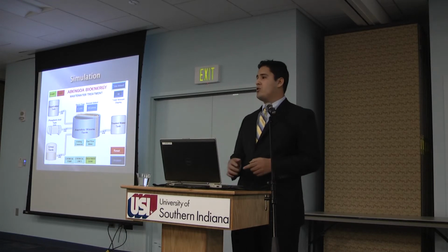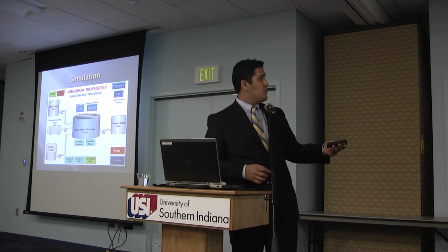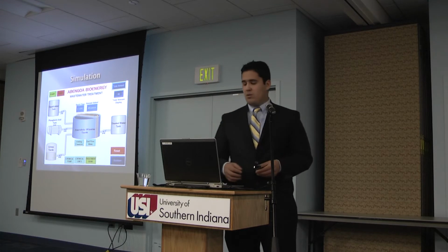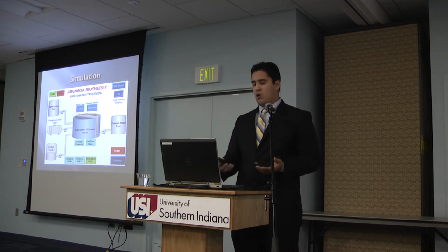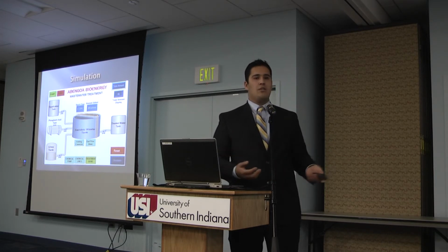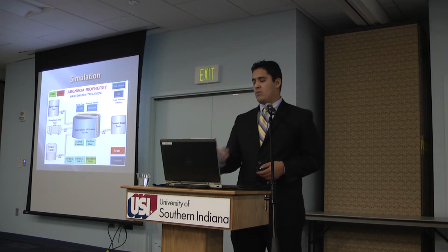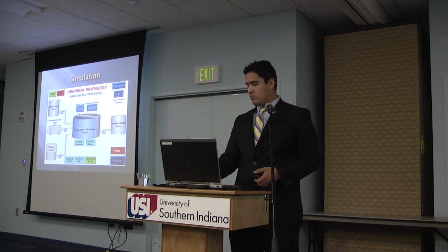There's no more chemical addition. The process has been finished. The amount added, as you may see, equals the total amount entered, and the treatment done light comes up. That lets the operator know the treatment has been done, and in order to start the treatment once again, it will have to get a new input for the next process.